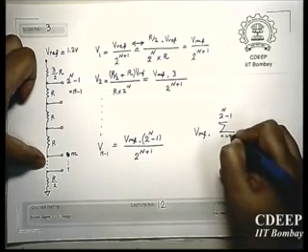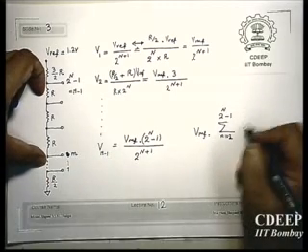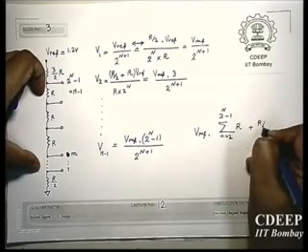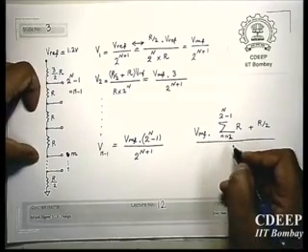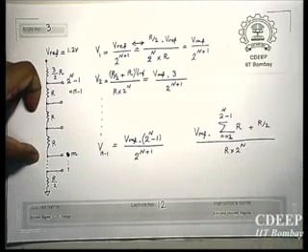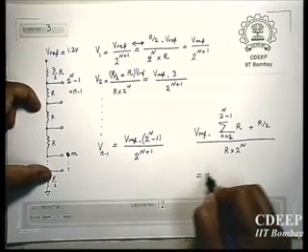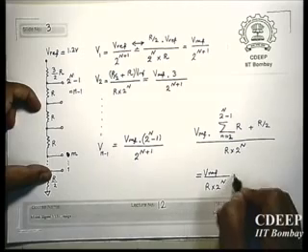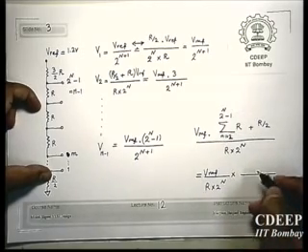In fact, this will be 2 because it will start from this R and then plus R upon 2, upon the whole value, which will be R into 2 to the power n. So this will be Vref, R into 2 to the power n, multiplied by, and this is 2 to the power n minus 1.